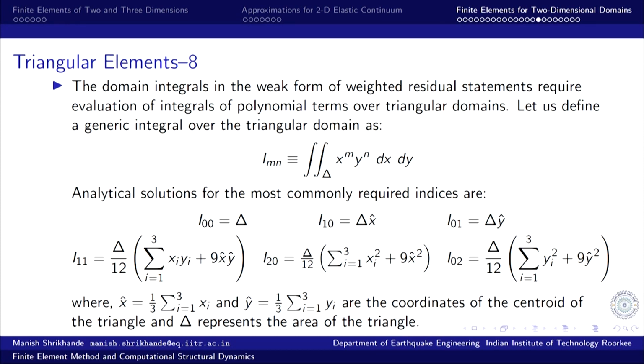Now, for triangular domains there are analytical expressions already available based on the powers m and n. Some of the commonly used integrals that we may need in this case of finite element approximation for triangular domains are these. I 0 0, the 0th order, a constant integrand, is only the area of the triangle. First power of x and 0th power of y is just the area multiplied by x hat, the x coordinate of the centroid.